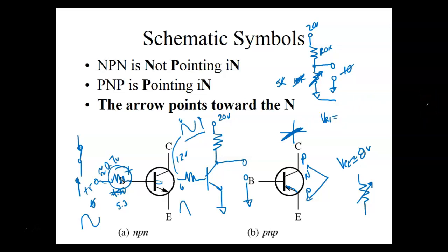And since we're only using 2 resistors, a lot of times you can do this in your head. I want the resistance across this, so it's the resistor, 5K, divided by total resistance, which would be what? 15K. Right off the bat, I know the K is dropped, right? You understand? And then I know that resistor is going to drop, instead of 1/2, 1/3.